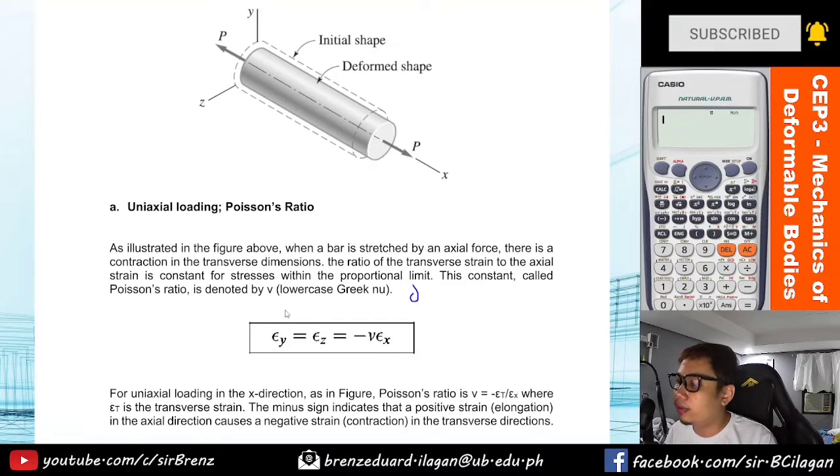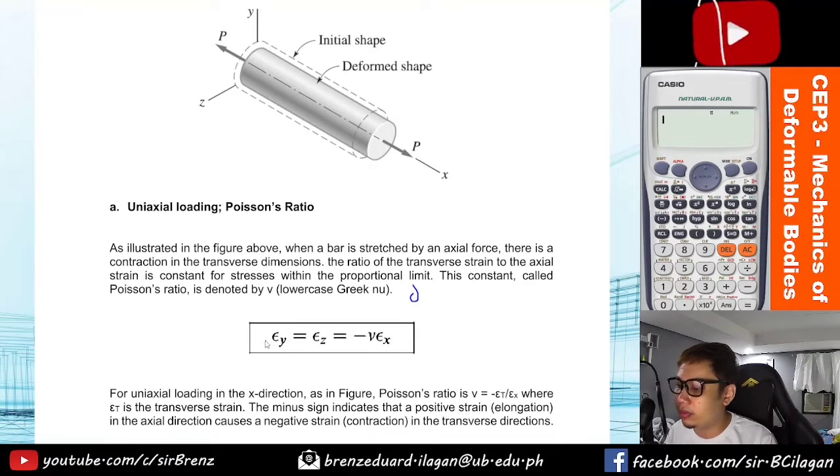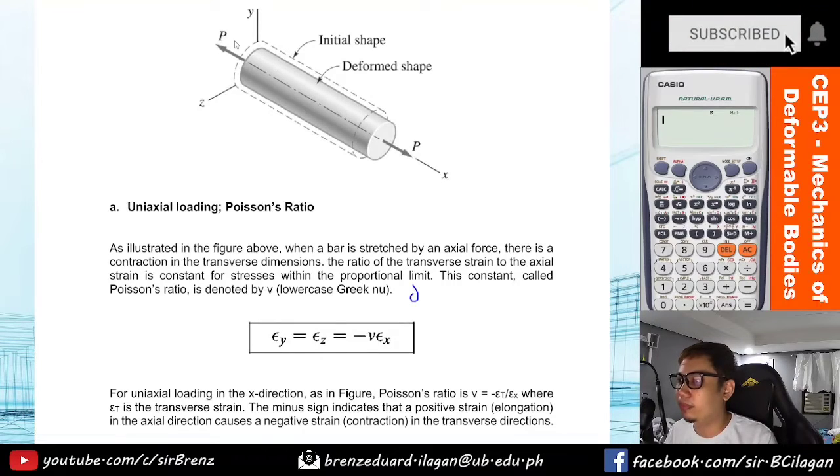Where the equation is given by this equation. The strain in y is equal to the strain in z, which is equal to negative nu times the strain with respect to the x direction. So as a reminder, wherever the actual force is, that is where the nu goes, in the strain in the x direction.